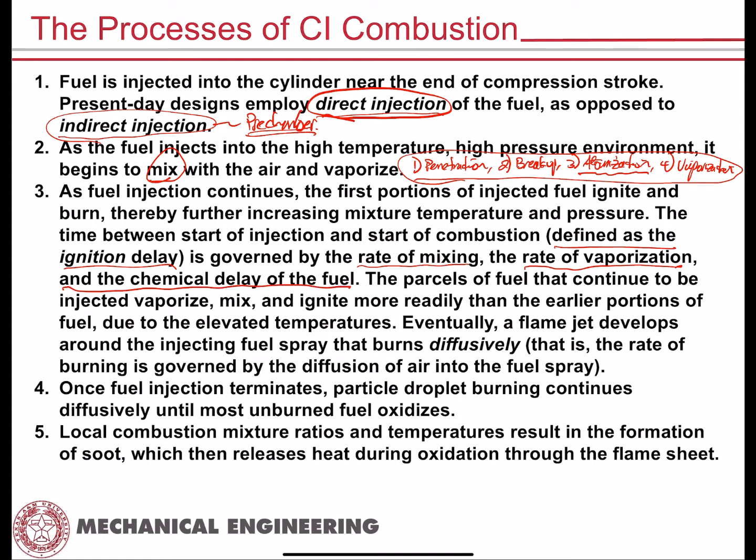All right, now, once you have combustion beginning, then the parcels of fuel that continue to be injected still have to undergo these processes. Mix, I put it out of order, so mix should go first. Mix, vaporize, and ignite. They can do this more readily than earlier portions because of the elevated temperatures. But eventually what happens is that these physical processes basically dominate the time it takes to get the fuel ready for ignition.